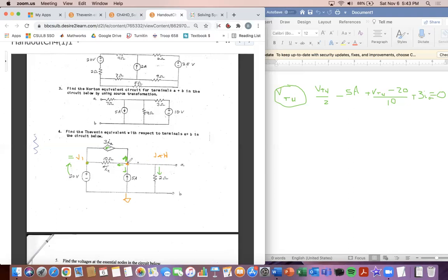I drew it over here to the right, just right before, because I always think of the voltage source with the series resistor for the Thevenin equivalent. I just drew it up there as a reminder for myself. I'm mainly concerned about the arrows, where the current is traveling. So let's say I create this node for V Thevenin. We know we need to draw arrows coming out of this point: one's going up, one's going here to the left, one's going down, one's going to the right.